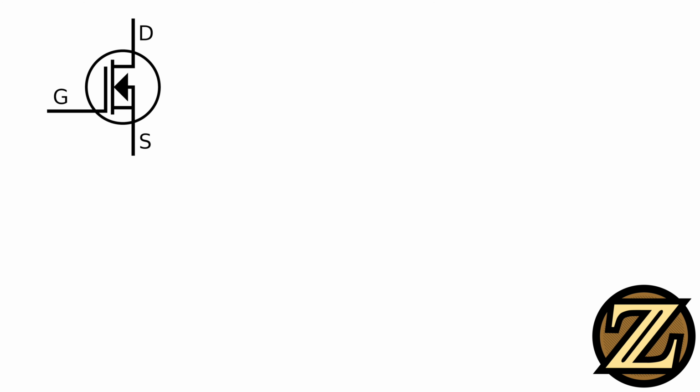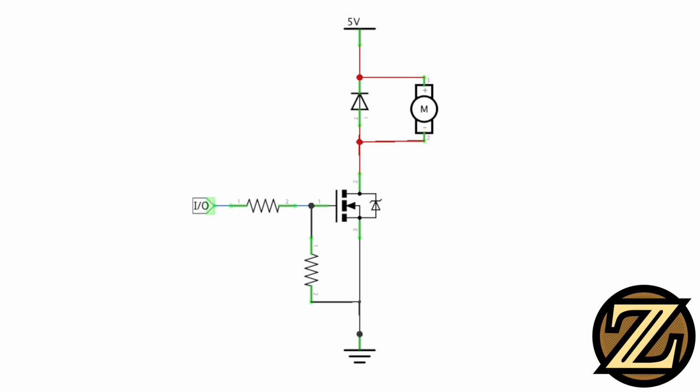Now let's look at using the N-Channel MOSFET. Here I have a circuit similar to the NPN BJT. We have a motor, flyback diode, transistor, gate resistor, and pull-down resistor. Again, the I/O can be a device such as an Arduino or a Raspberry Pi. Our pull-down resistor pulls the gate low when it is otherwise left floating. When we apply 5 volts to the gate, we build up charge on the gate. Unlike a BJT, current does not flow through the transistor.